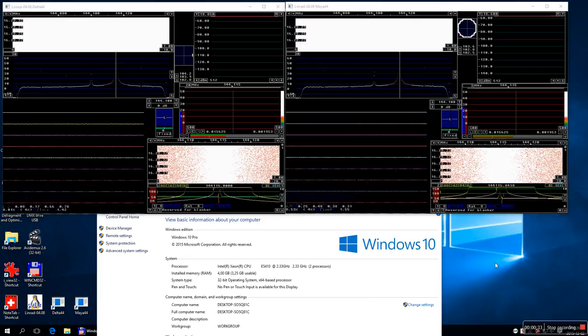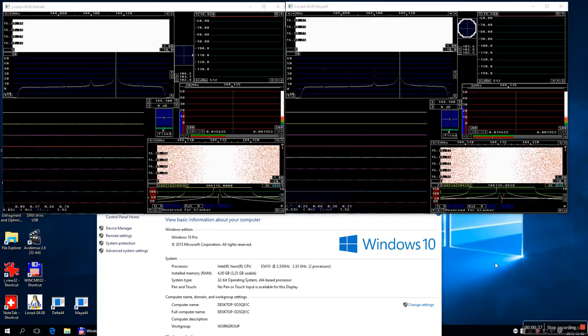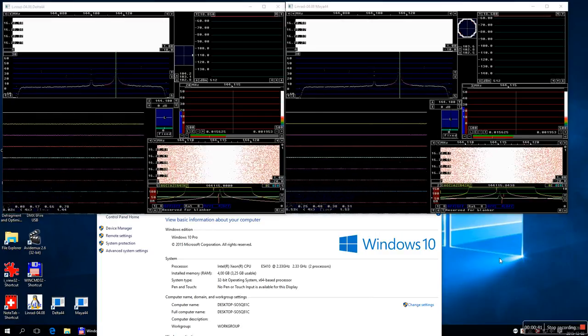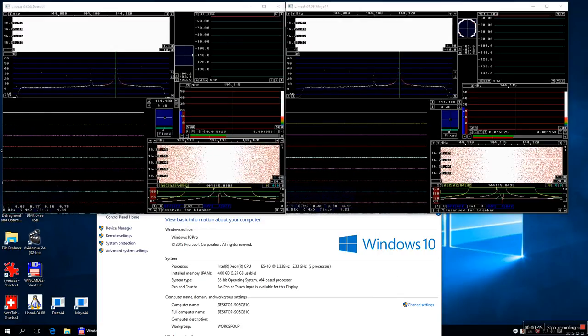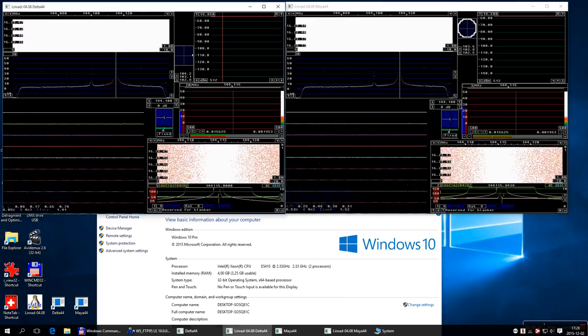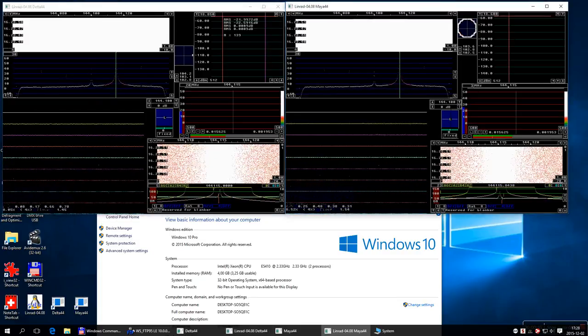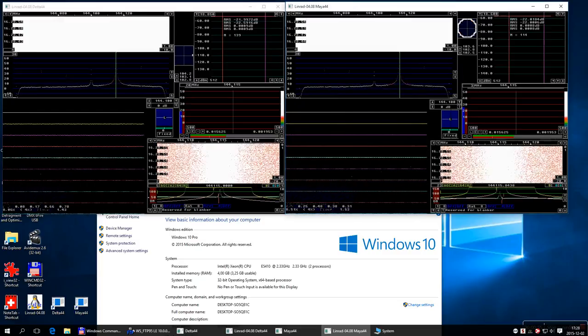The S-meter graph is calibrated to show the signal level that I have measured to be present on the antenna connectors of the IQ Plus. That's minus 22 dBm, and you can see that's what the evaluation says here on both systems.